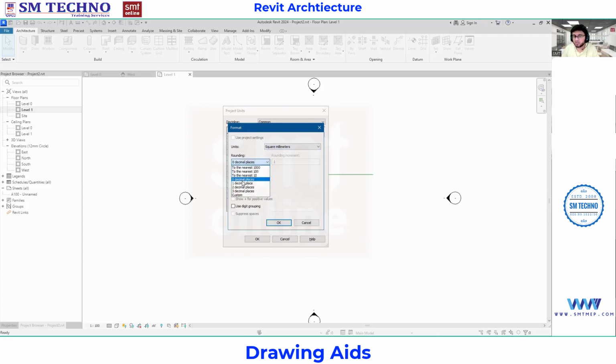Rounding decimal 1 or 2, like 3000.1, that will be the value. If you go with 2 decimals, what will happen? 0.01, 0.02, those things will come. But for millimeters, 1 decimal is enough. And the symbol we get when we mark the area will be mm square because we are working with square millimeters. If you want to customize, you can customize also.